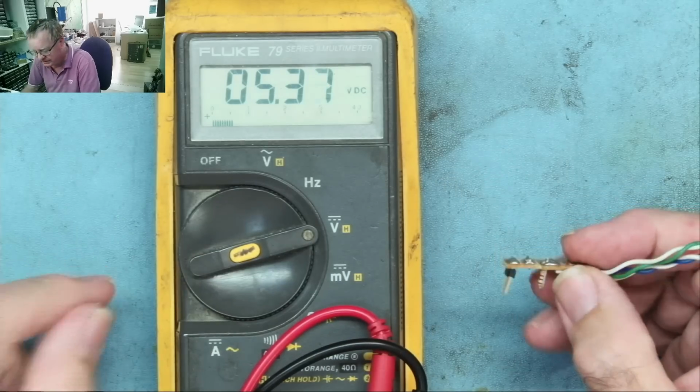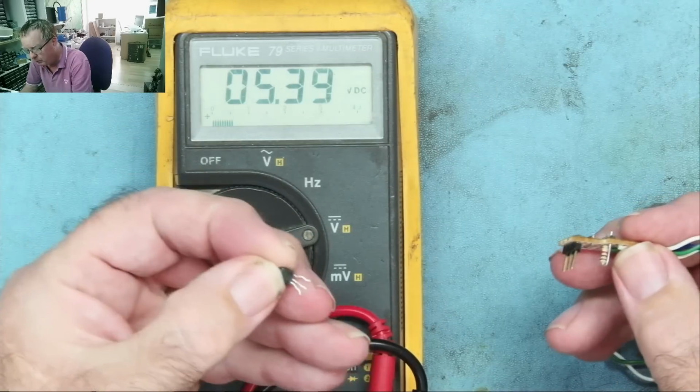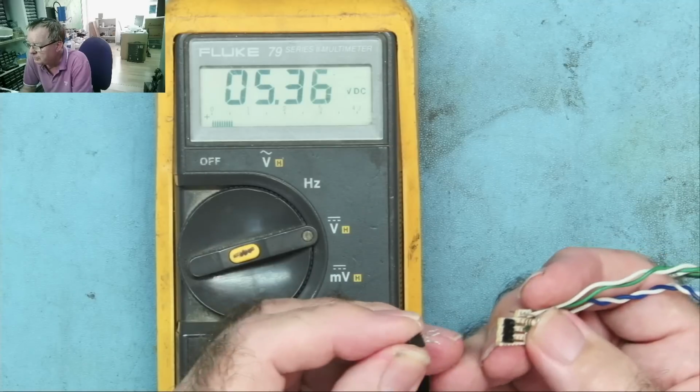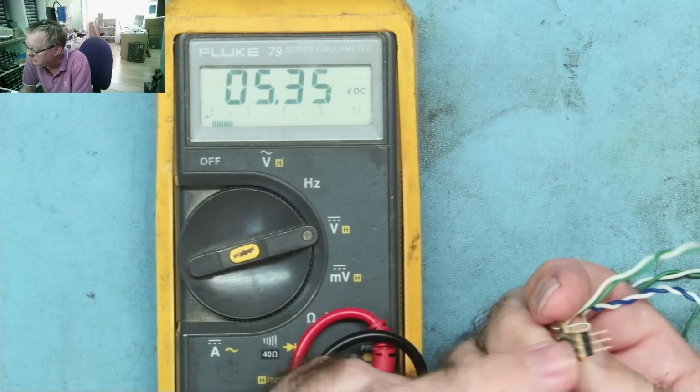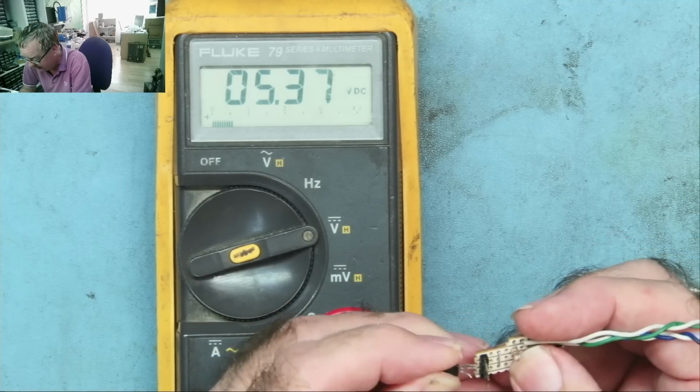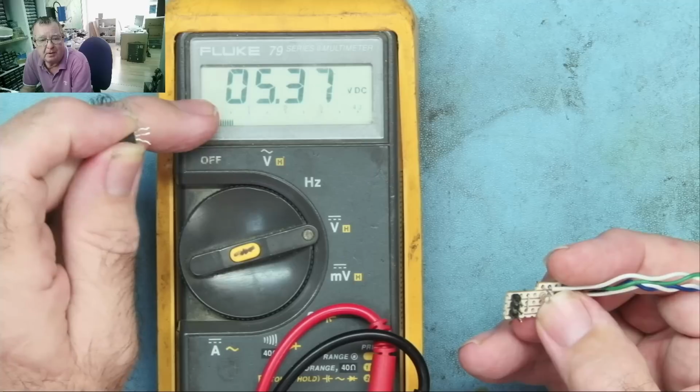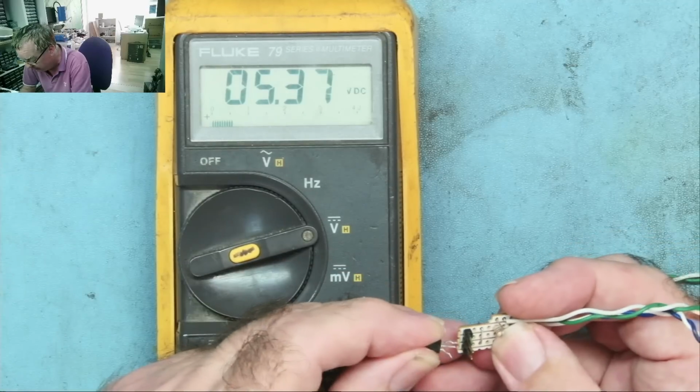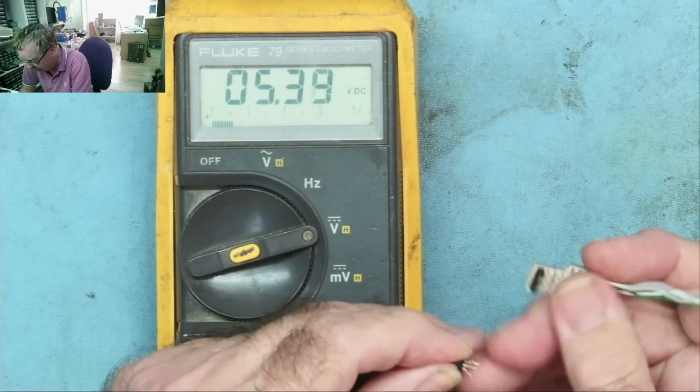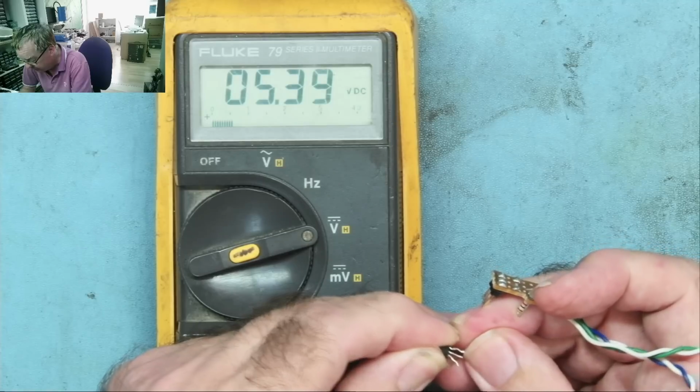Here then is the tester, and here is a TL431. So we just connect the 3 pins to these pins or to the tracks, wherever is the easiest. My power supply is currently set to about 5.3 volts. I say it's not critical, but as long as it's more than 2.5.